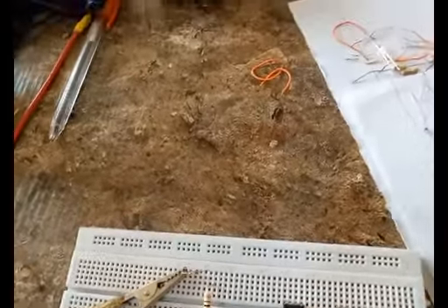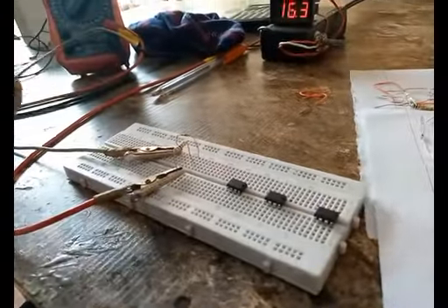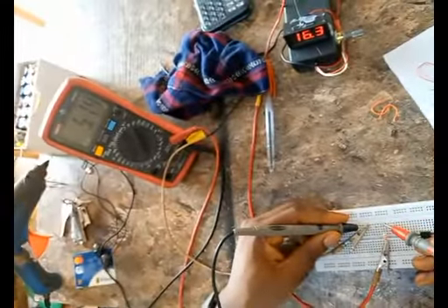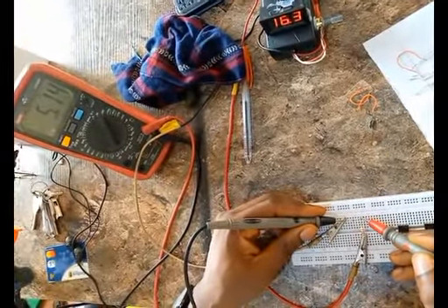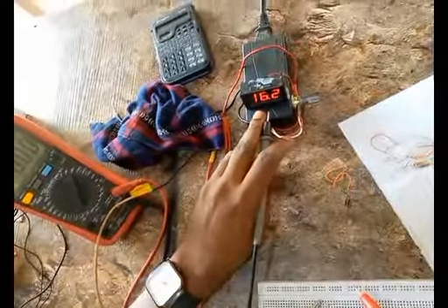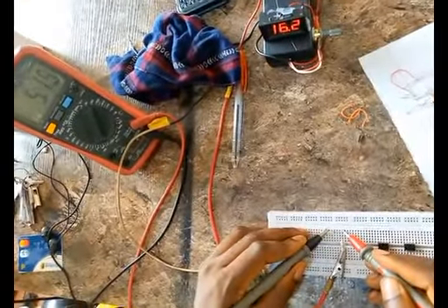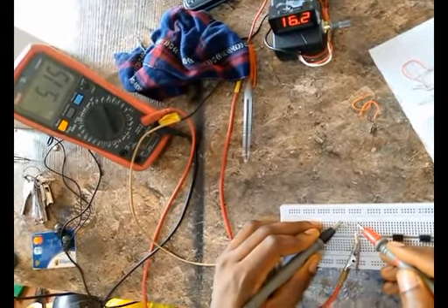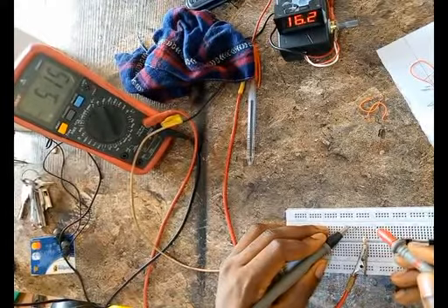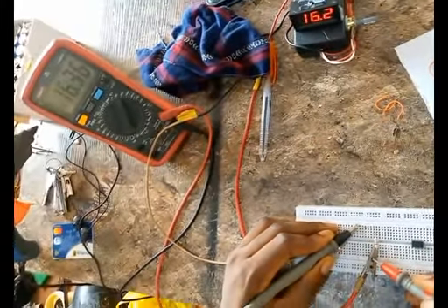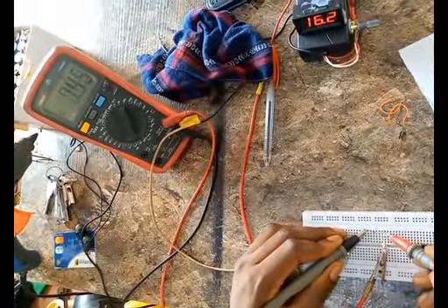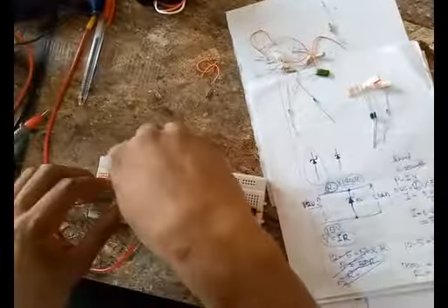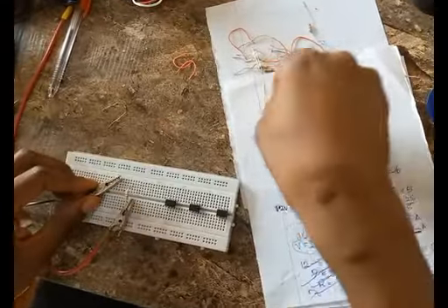Now, let's see how many volts we have across the Zener diode terminals. We see that it keeps it at what? 5.1 volts. Even though we have 16 volts entry, what we have at its terminal is 5.15. So it clips it at that voltage. All right. Now, how do you know what's entering? Look at what is entering: 16 volts. And what is coming out is 5.1. Let's replace this with another one, maybe a 12-volt Zener diode, and see how it clamps it.